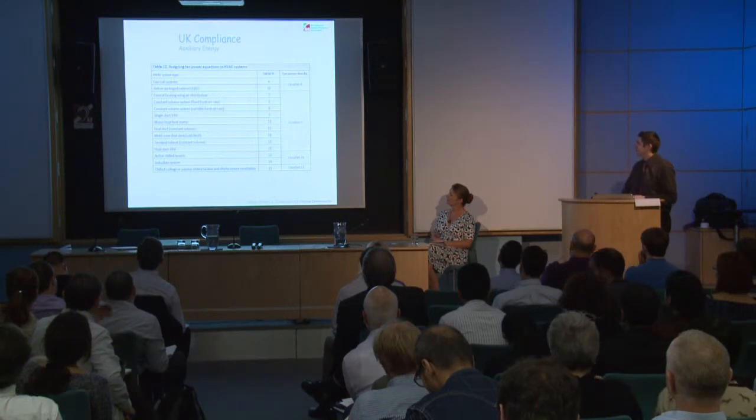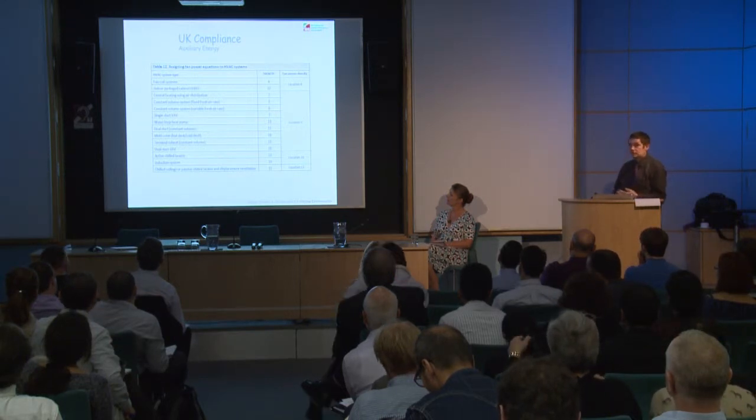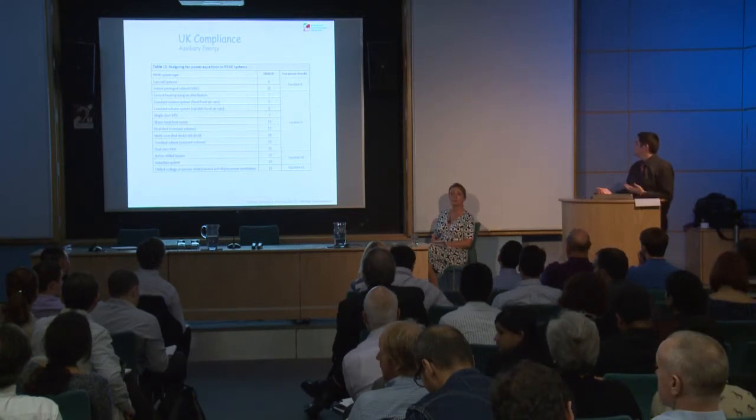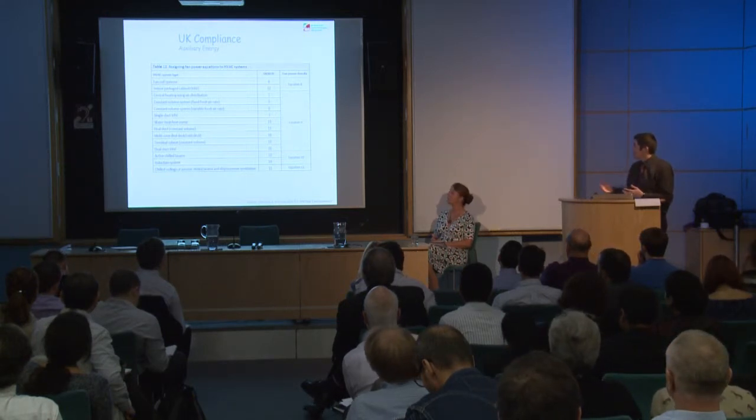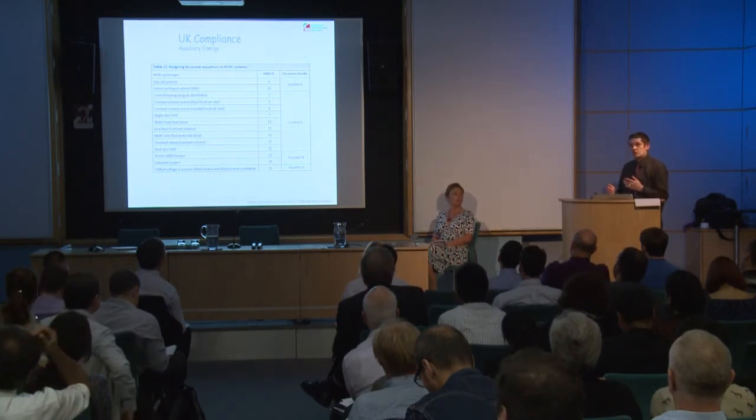Now, I think that's again one of the limitations of the methodology, in that you're looking to pick a system that's going to give you the best compliance result, which may not necessarily be the best result for your real building. So it's always worth considering, when making design decisions based on this, what the implications are for the real design as well. Is a fan coil system really going to be the most efficient, best performing and most appropriate system for this building type, rather than simply picking it because the compliance assessment says that's the way to go?